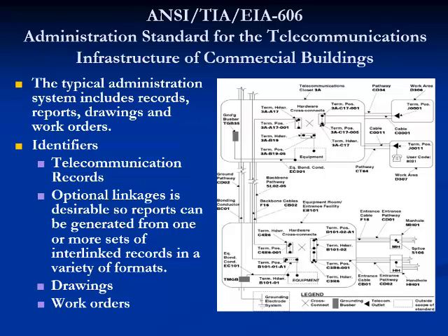Administration can be accomplished with paper records, but in today's increasingly complex telecommunication environment, effective administration is enhanced by the use of computer-based systems. Each space, pathway, cable termination point, and ground is assigned a unique identifier number that can be simply encoded to provide supplemental information.